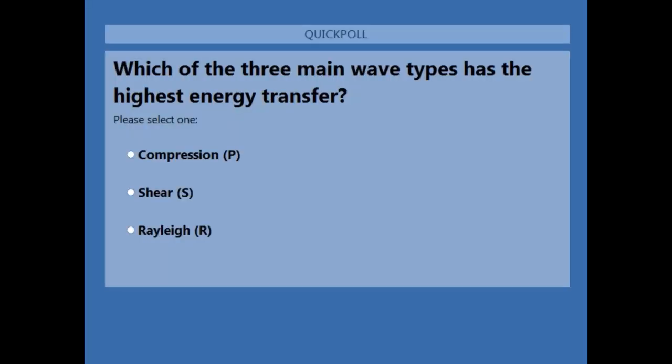Okay, we're going to get into some questions now. Question number 1. In the interest of time, there's a few questions here. The first one being, is there a damage threshold for underground utilities? That's typically up to the utility owner. But I will say that National Grid, their standard threshold is 2 inches per second. And that's somewhat consistent with a lot of the other utility companies.